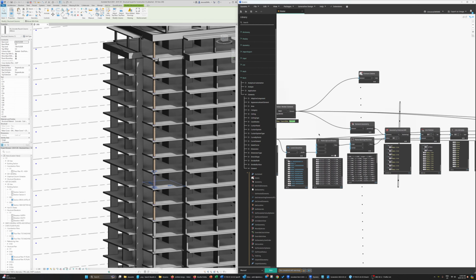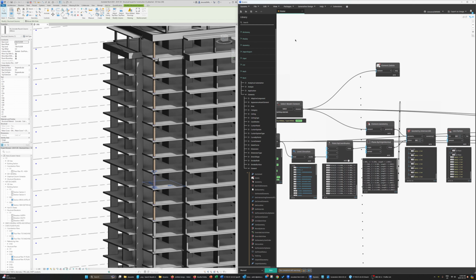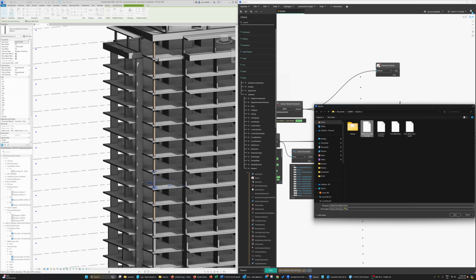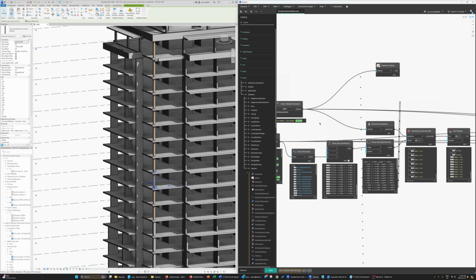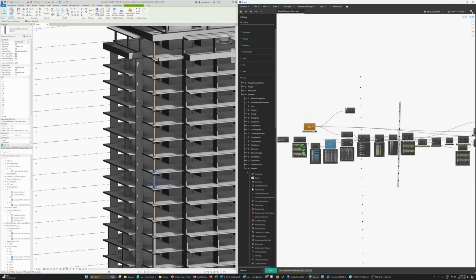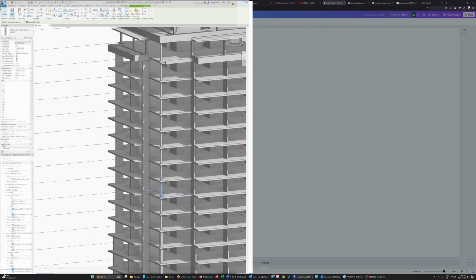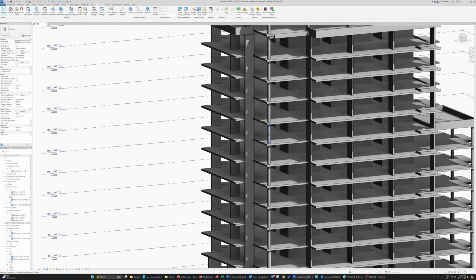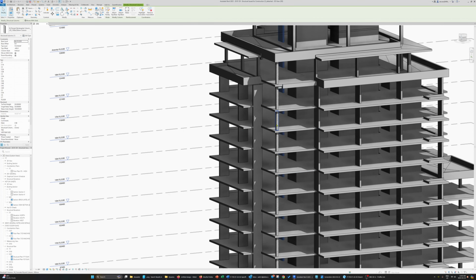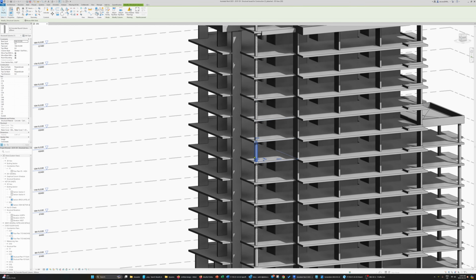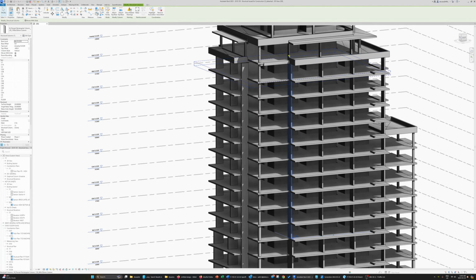So we can do this with any type of component, which is the advantage. Now we can just save this script potentially, and I'll call this revision 1. And obviously it does provide us with a bunch of things and a bunch of levels. So if I close this, if I want to go back into my level, now we can visualize I don't have this problem anymore. And I'm able to do this across the board. The only difference is I would have to scale to select all my columns, and it would do a much more intense job, but I like to control these individually, just because sometimes they're not the same profile, they have different shapes. They could be changing slightly.